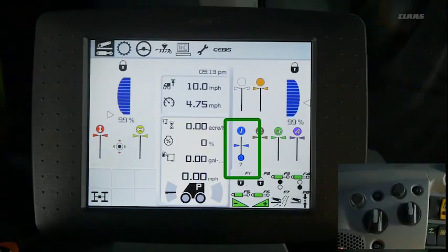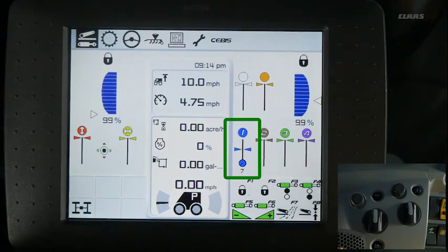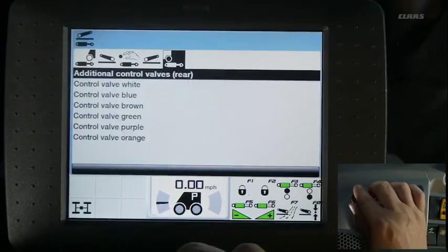When you return to the working screen, notice that the blue valve arrows have now moved from 100% down to 65%, and the blue timer icon shows a 7 for 7 seconds of on-time demand. The remaining values can be adjusted the same way.